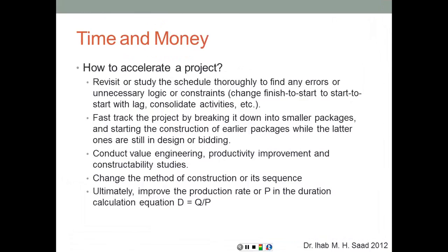How to accelerate the project? There are different ways. The first of which is to revisit or study the schedule thoroughly to find any errors or unnecessary logics or constraints. So, for example, if we have some activities that are done on a finish-to-start basis, what if we can do them on a start-to-start basis or with lag, or finish-to-start with overlap, so that we would shorten the duration of completion?